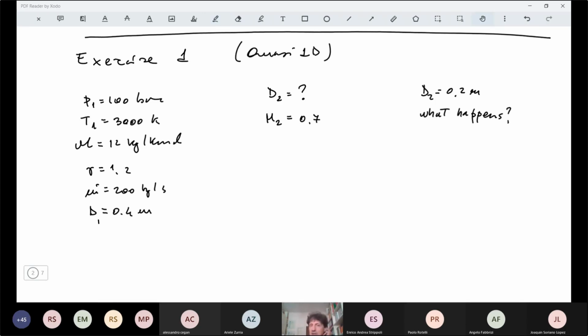So of course, this is the case of isentropic flow. We have only area change, so Sm and Se are equal to 0. The only driver is the area change. As you know, for this case, we can exploit the isentropic relations, and we know that total temperature and total pressure will be constant.